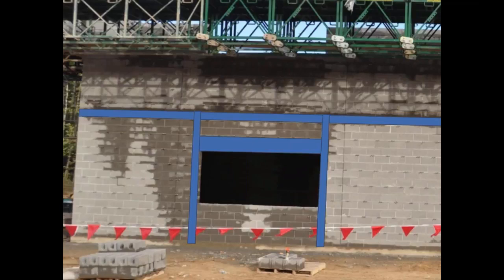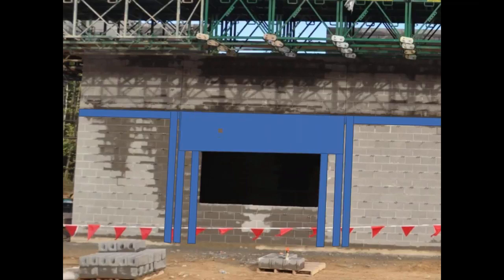This is a top wall. There's a bearing wall, a two-story school. There's a lot of times where adding a little bit of extra depth is something that they're just going to do anyway. They don't want to start and stop grout multiple times. So sometimes when I'm talking about, I don't need 4 courses, I don't need 5 or 6 courses, sometimes you're going to get it anyway just because of the ease of construction to grout everything solid above an opening, especially in a multiple story scenario.